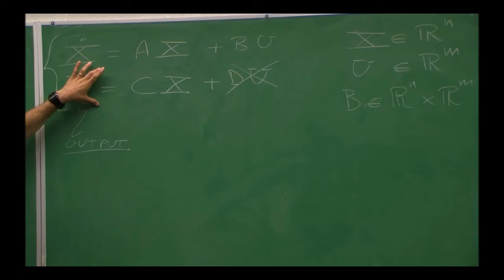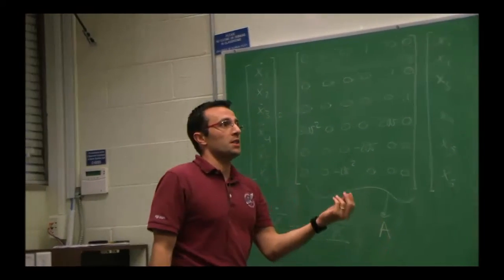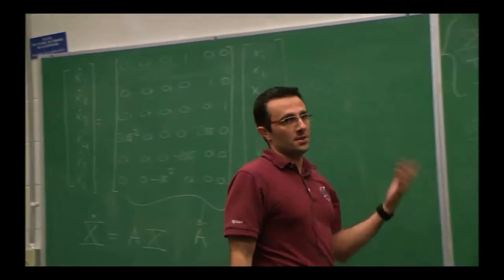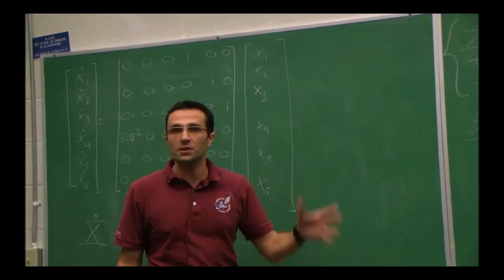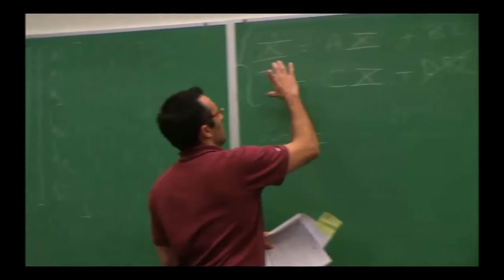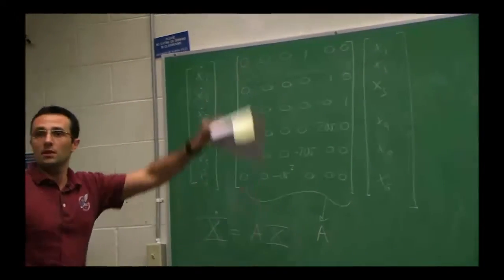Depends. If I have a spacecraft that is changing orientation, actually let's put it this way. If I have a spacecraft below the GPS constellation, nowadays spacecraft can carry a GPS receiver, so they can know their position more or less the same way you do it here. But that is what is measured. You can say that the x, y, and z are measured. The velocity is not usually directly measured. It's derived from measurements with some Kalman filters or other procedures, but you don't measure that quantity directly. Okay? So what I'm saying is that these would be what you can measure. This is what people do when they talk about state space. They find out what are the variables that they can measure. Is this clear?